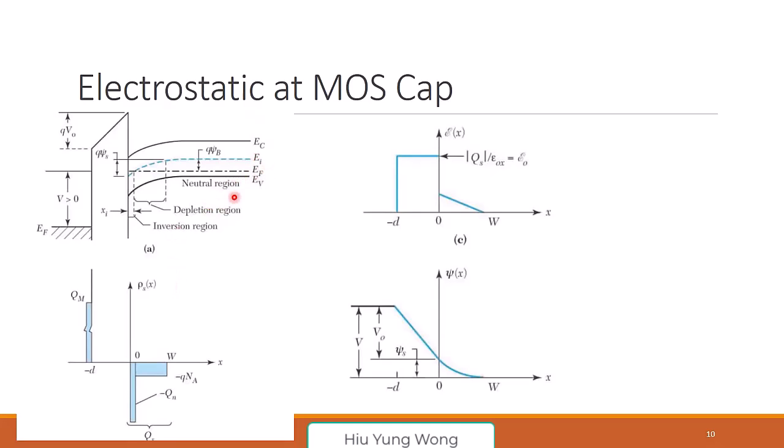Okay, it is labeled already, but can you tell me, do we apply positive or negative bias to the gate? Based on how it draws the Fermi level. What can make you push down? Positive voltage. Positive, yeah. It is set here, right? But still from here, this is P-type. So it's like MOS. But anyway, we put the positive gate bias here, right? So it pulled down. So now can you tell me, is it an inversion, accumulation, or depletion?